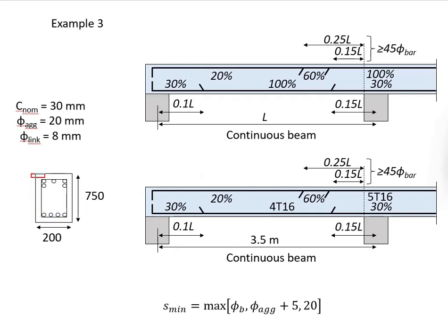Of course, you can have 5 reinforcement bars laying at the same level. But due to the relatively small width of the beam, that is not likely the case. The second option for you will be having the 5 reinforcement bars arranged in this manner.